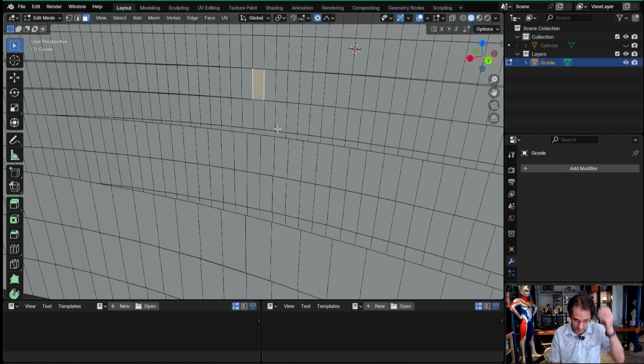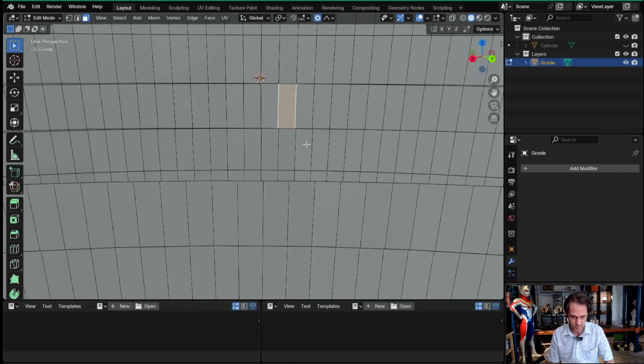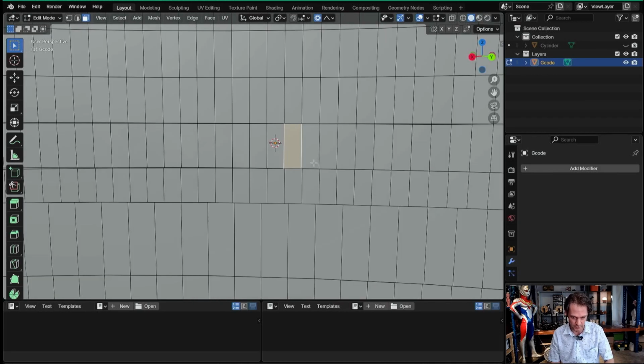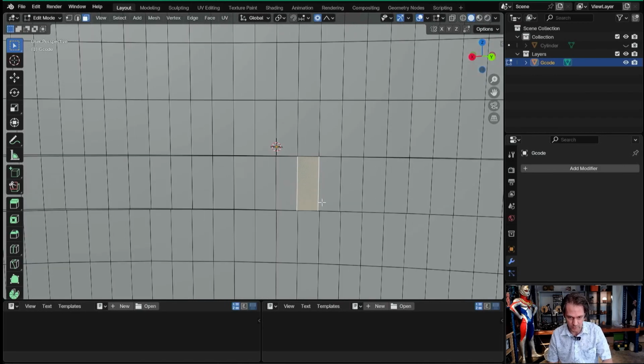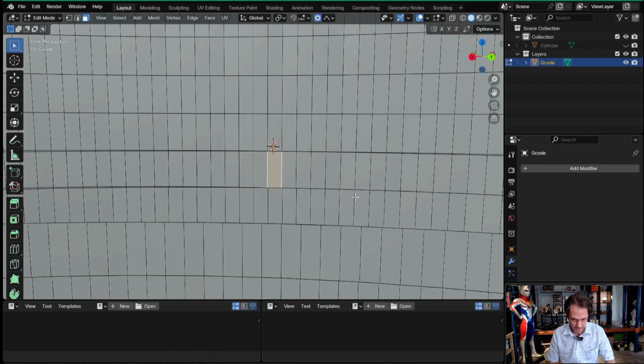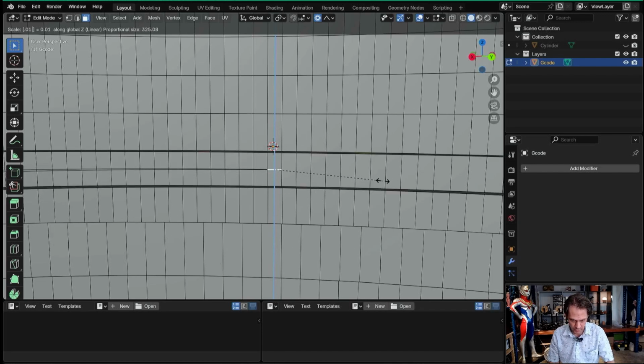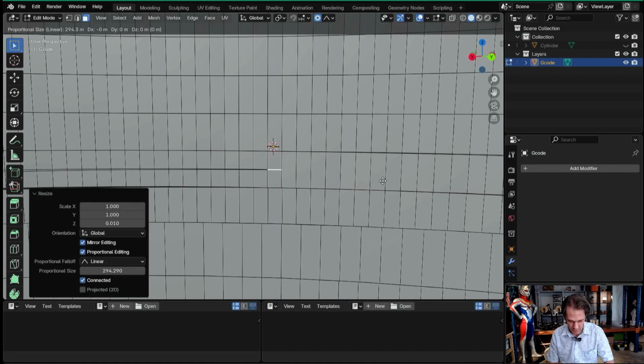So this is the start of the Gcode, but the start of the Gcode is extruding at full volume over the top of the last layer, which creates an over-extrusion for that. So I want to do the same thing again and shrink it down. So I go scale Z 0.01, and then bring that right round till just about there, and G Z, move it down.